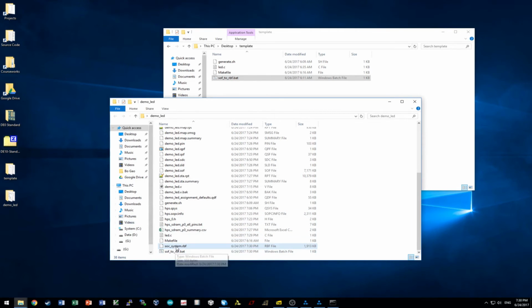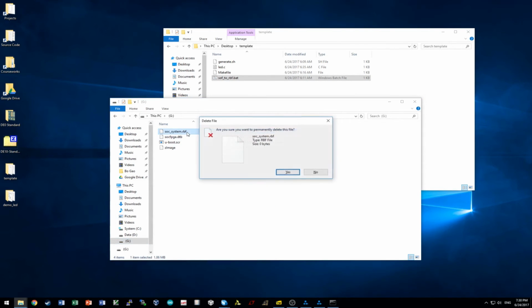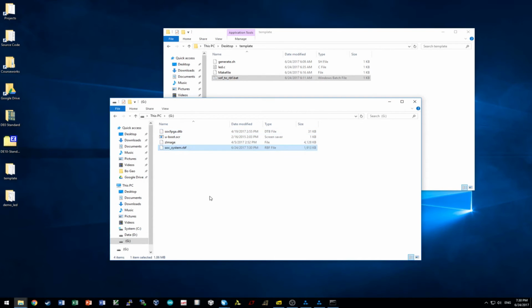Okay. So let's dump this to the FPGA. Yes, I have the card. So first let's copy this file, and that's the previous one. Let's remove that one. Let's paste it. And keep in mind, this only works for the console version of the Linux. If you use the LXD version, it will not boot because it expects some other devices. As I said before, it pretty much expects a lot of other devices on the AXI bus, which we don't have. We have a fairly simple QSys design. So in this case, we have to use the DTB provided with the console version of the distribution.